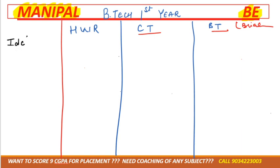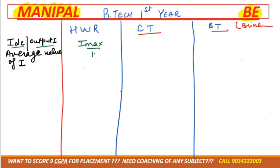Okay, IDC, or they can say output current. As you know, a rectifier converts AC, so the output current will be DC, or sometimes they'll say average value of current. Okay, so average value of current is also IDC only, don't get confused. The name is same. For half wave rectifier it is Imax by pi, for center tap it is 2 Imax by pi, and for this one also 2 Imax by pi.